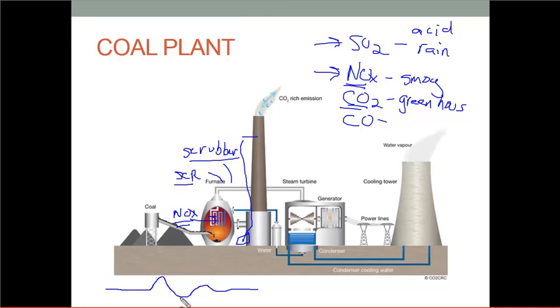It's harder to keep this thing going as cleanly as possible when the load's changing. And of course, you've also got particulate emissions and opacity issues because nobody wants to see a bunch of smoke coming out of the stack. So tuning this boiler when it's following load like this becomes an issue, and it's an operational problem for the power plant operator.